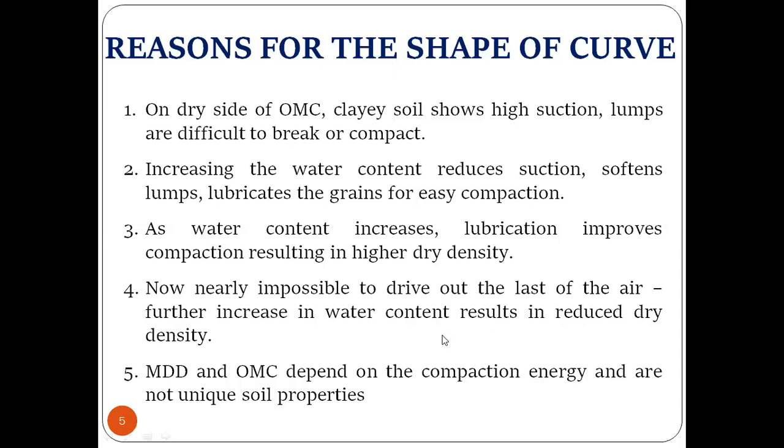Further increasing the water content results in reducing the dry density. So I can remove the air up to some point, right? After that, when you add more water, the air is still not coming out, then what happens? This water will go and stay in those voids, right? So what happens? There is a reduction in the dry density.